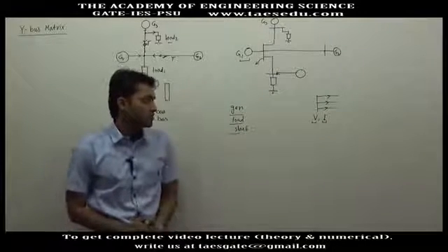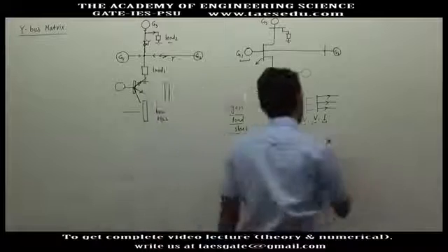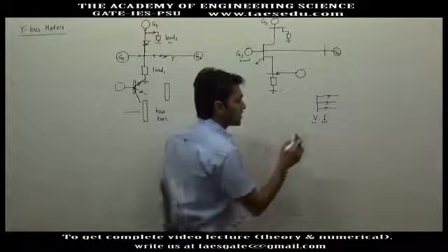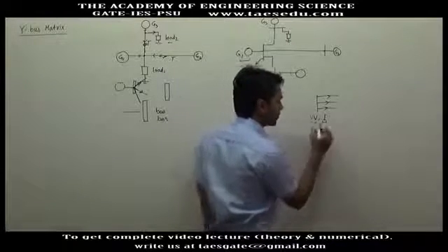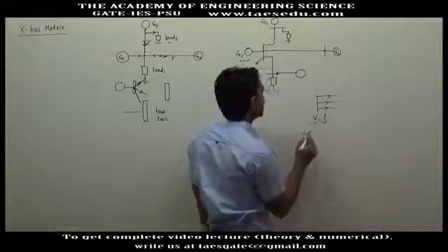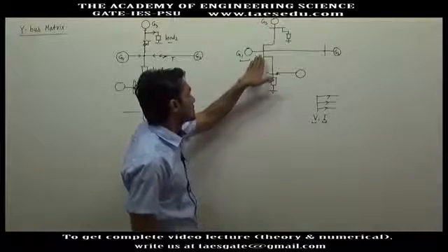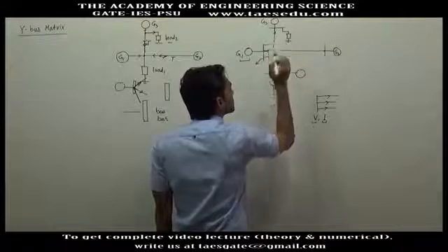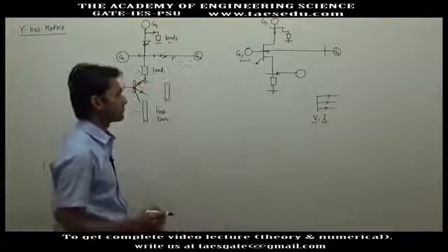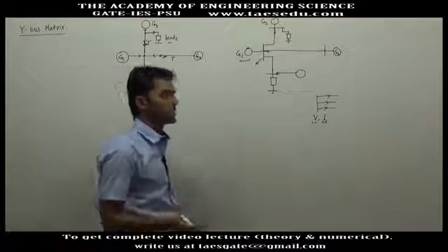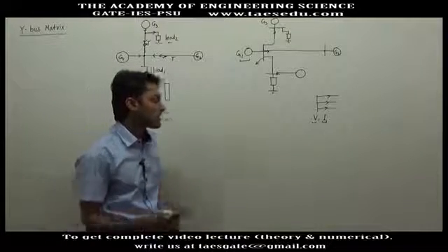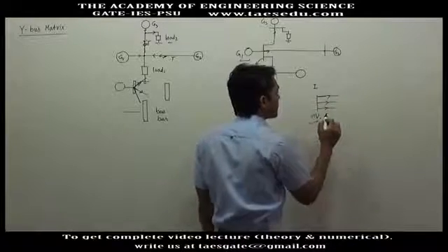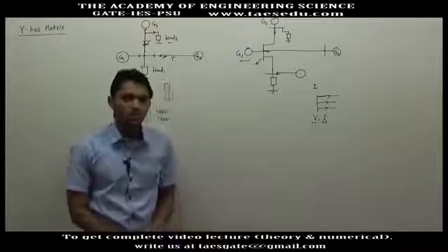In general, the voltage of any bus will not only depend upon the current flowing through this bus only. In general, the voltage at any bus, let's say this bus, will depend upon all the currents, and the current at any bus will depend upon the voltages of all the buses in general.